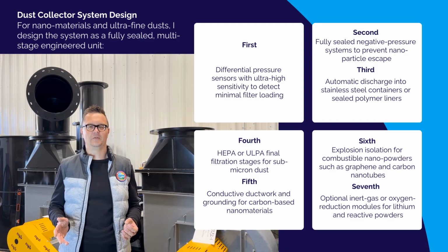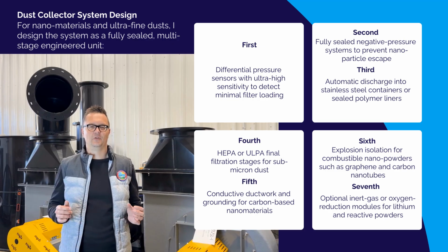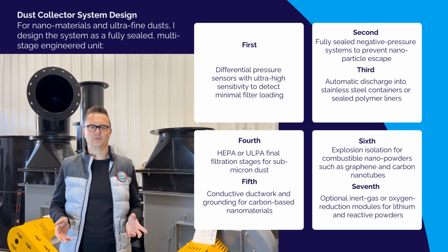Fifth, conductive ductwork and grounding for carbon-based nanomaterials. Sixth, explosion isolation for combustible nanopowders such as graphene and carbon nanotubes. Seventh, optional inert gas or oxygen reduction modules for lithium and reactive powders. This is high-precision engineering, not general-purpose dust control.